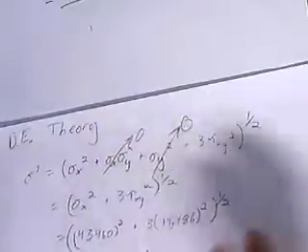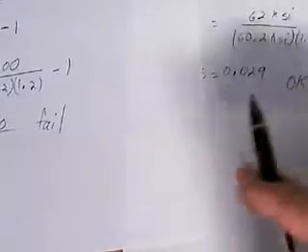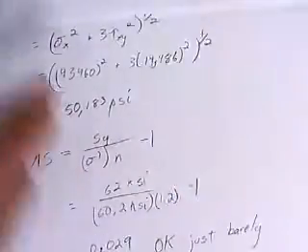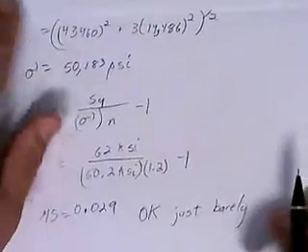So as far as the comparison goes they're actually decently close. If you look at the difference between them, you've got 0.029 and negative 0.01. So there's a difference of 0.03 between the two of them, but that changes as you get bigger and bigger in those margins of safety. But there you go. That's how you use maximum shear stress theory and distortion energy theory.